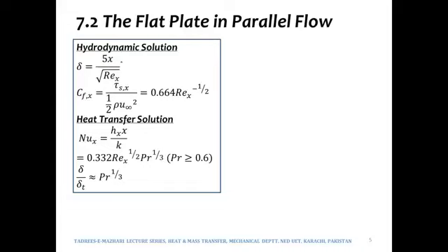scientist, and what he did was that he plotted a velocity profile, u by u infinity. So it was a non-dimensional velocity profile. He took that velocity profile u by u infinity and plotted it against another non-dimensional distance, y by delta. So both of the parameters were non-dimensional, u by u infinity and y by delta, and of course all those things have their usual meanings.